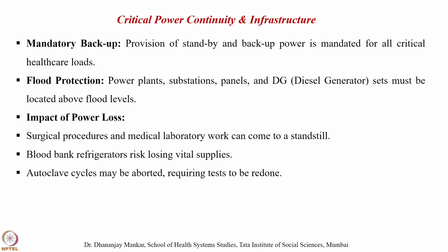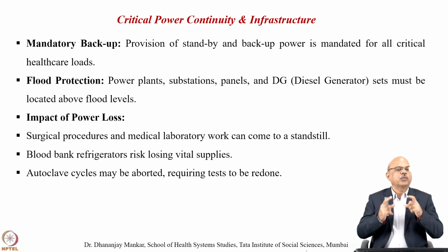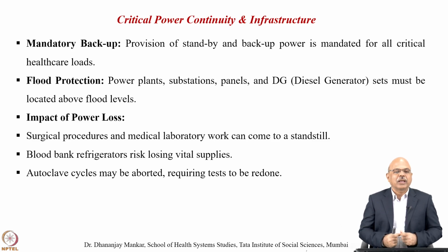Now for critical power continuity and infrastructure. You need to have a mandatory backup, you need to work on flood protection, and you need to consider the impact of power loss. The reason for mandatory backup is that standby and backup power is provided for all critical healthcare loads. For flood protection, power plant, substations, panels and DG setups must be located above the flood level, where you can tackle it more easily.